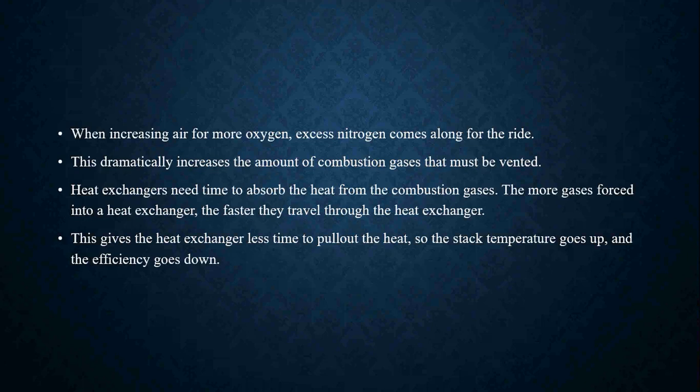If it's going too fast, your furnace is losing the heat faster than it can be used. Okay? If it's going too fast, it gives the heat exchanger less time to pull that heat out and use it in the space. It's just going to go right out the chimney, and it's lost energy. Your efficiency is going to go down.